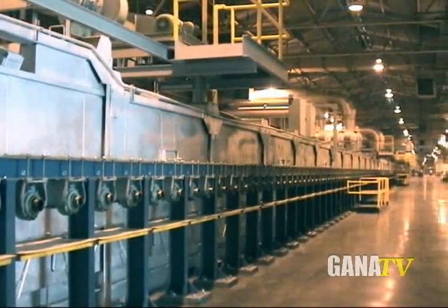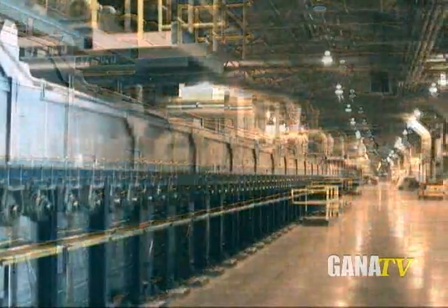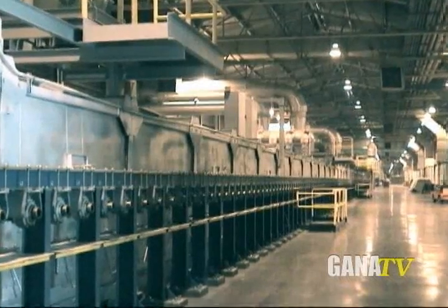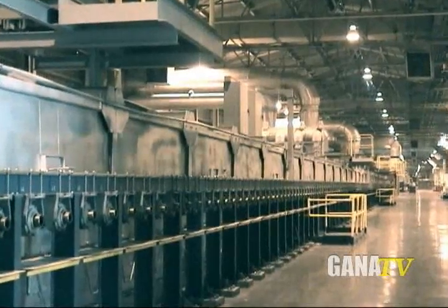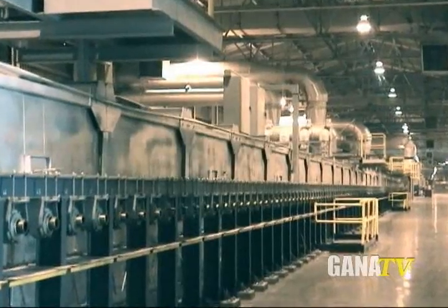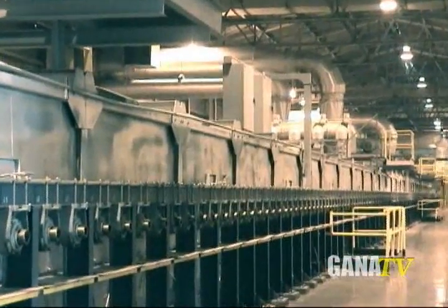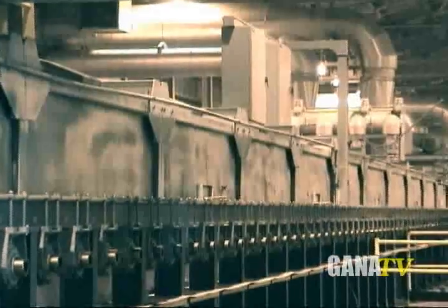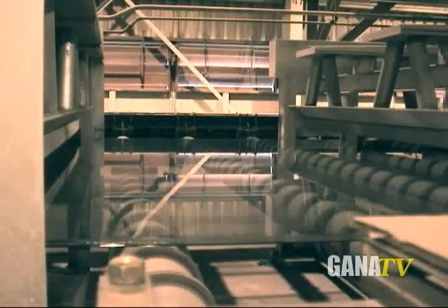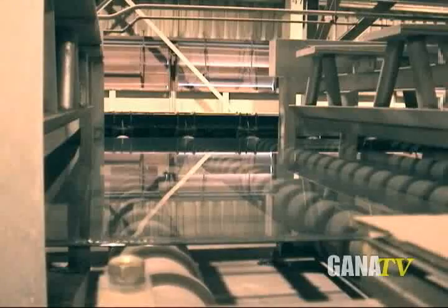When the glass emerges from the tin bath into the annealing layer, it is hardened to the point of preventing marking or distortion by the conveyor rollers which move it through the layer. In the annealing layer, the temperature of the glass is slowly cooled from 1100 degrees to 200 degrees Fahrenheit in a length of approximately 800 feet.